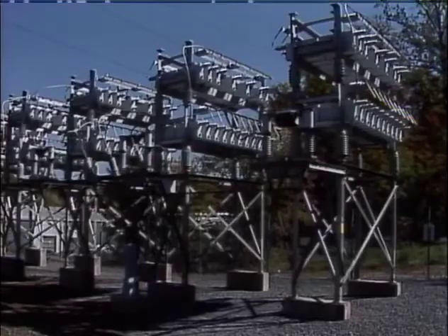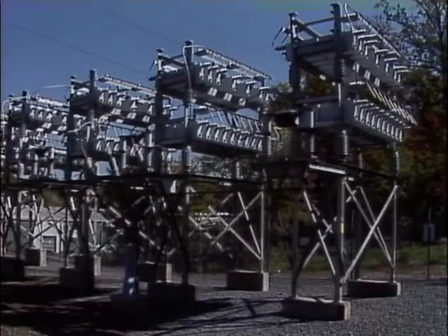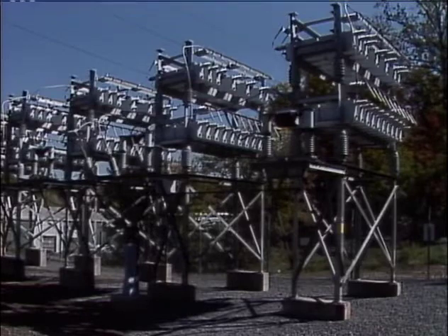The currents are measured and totaled for each of the other two phases in the bank. The total currents for each of the three phases should be equal within the manufacturer's or company's allowed tolerance. If the phases aren't balanced, capacitors with high current measurements in one phase are exchanged with capacitors with low current measurements in the other phases until the phases are balanced.